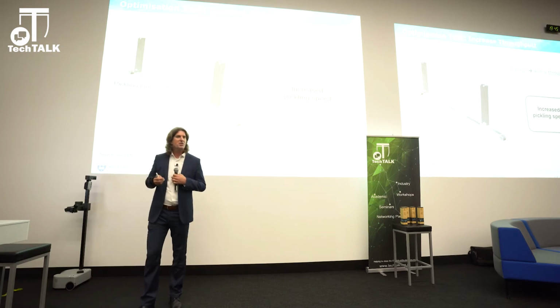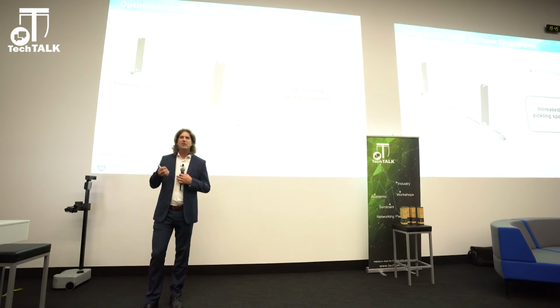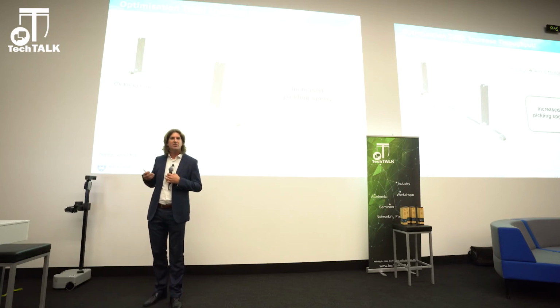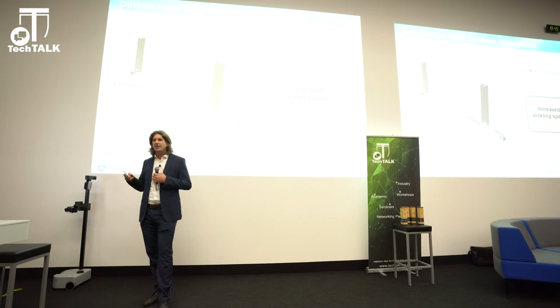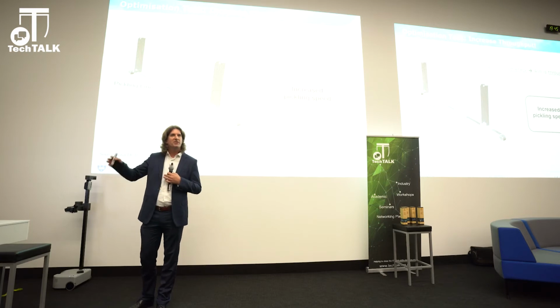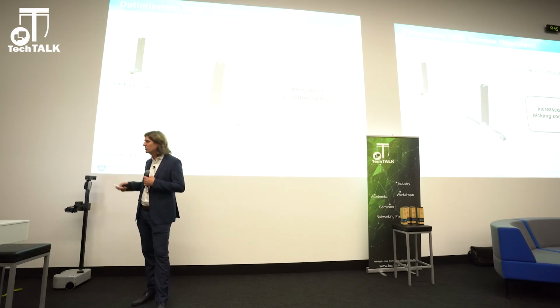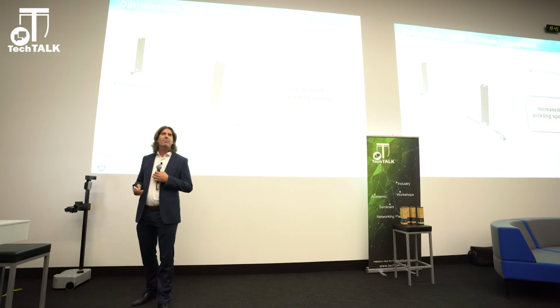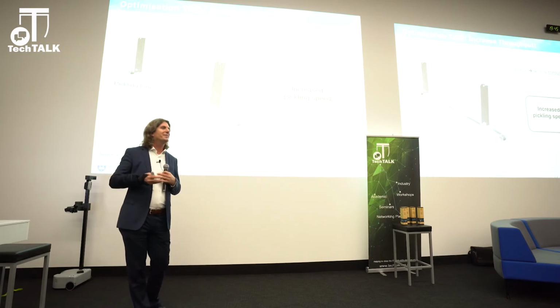And because the surface is so hot, there is scale, a kind of rust growing on that surface, which has to be removed before it can further reduce in thickness in the cold rolling process. That's where it's coming into a pickling line. These are acid tanks where you, in a continuous way, transport your strips through these acid tanks, and that scale is removed. So to improve that process, these coils should arrive warm instead of cold.